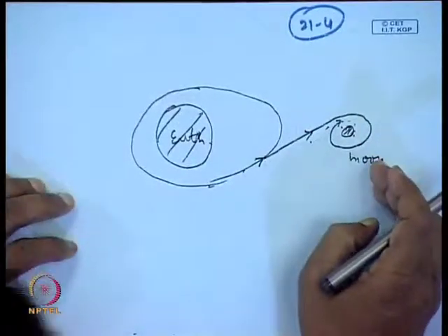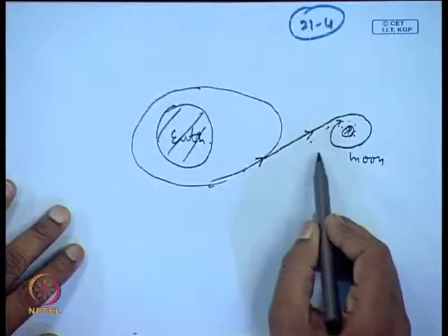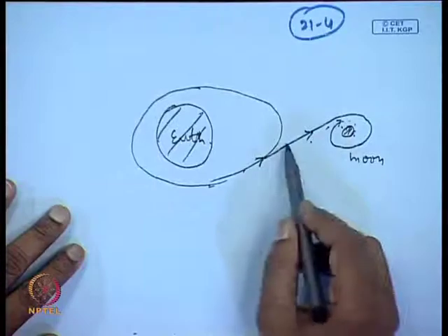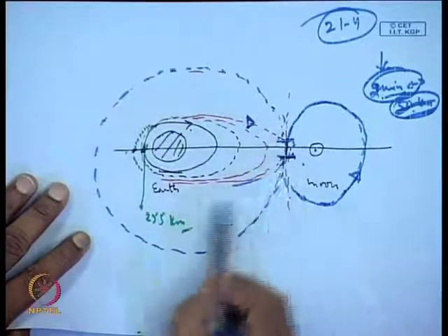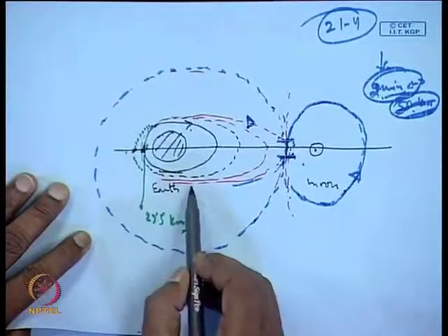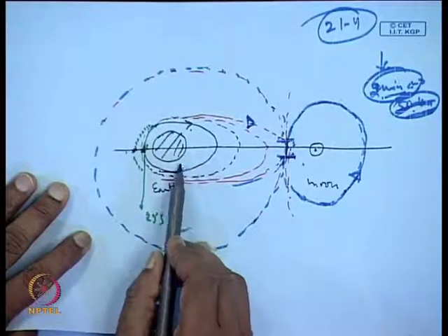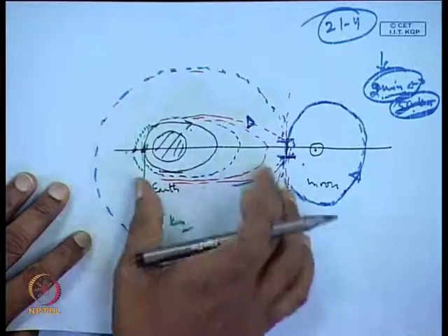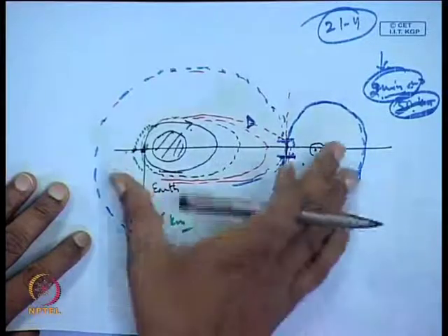Various kinds of trajectory transfer are possible, and it depends on how much confidence you have in the maneuver. If you have done this kind of maneuver already, then it is easy to do it. This kind of maneuver, in fact, ISRO has done for transfer from the GTO to the geostationary orbit. From the geotransfer orbit to the geosynchronous orbit, the satellites were already raised using this method, so it was very easy for them, and in fact these technologies were mastered. So, the foolproof method was utilized for doing this trajectory transfer.